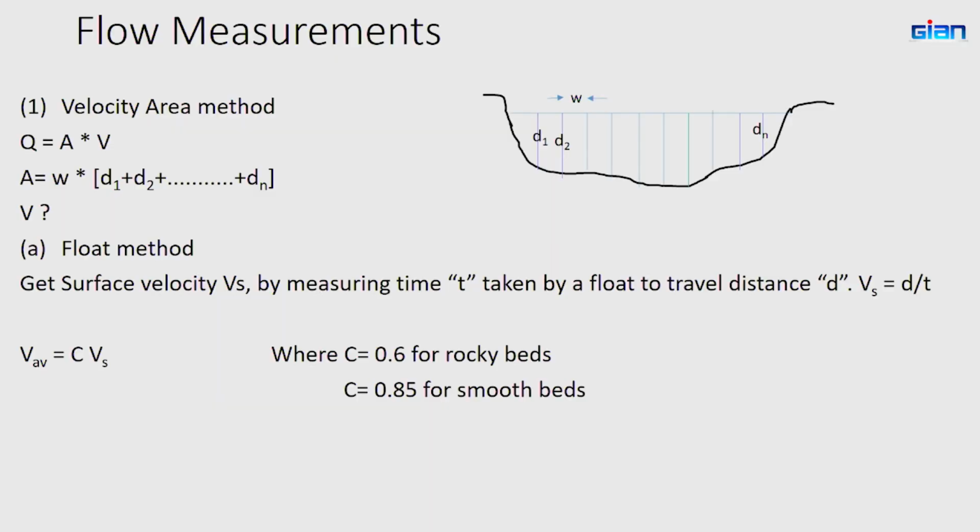Therefore, once you have gone up to this stage, it is good to measure the water flow rate in your river, and to have at least a few months, so at least one year's actual measurements, to confirm whether what the hydrologist has given is in agreement with the actual measurements. For that we will construct a measuring weir across the river, or else we can use an approximate method.